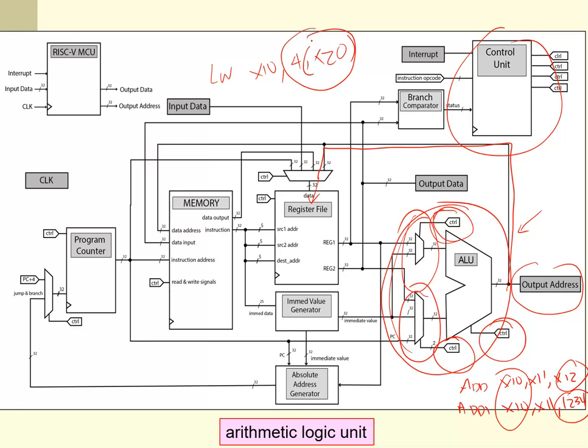So this is arbitrary. If we didn't use the ALU, we would have to put another adder in there, which is extra hardware, but this is a matter of reusing some of the functionality that we already have in here to do this calculation. Remember, this calculation we need to do to calculate the absolute address to, we'll say, get that data from, since this is a load instruction.